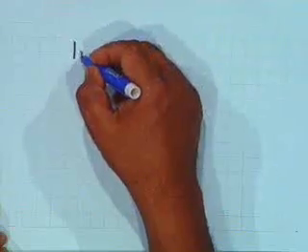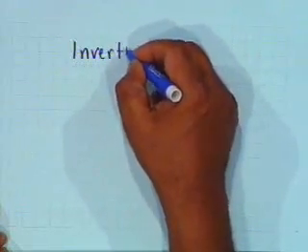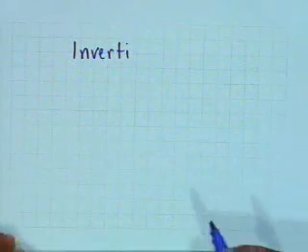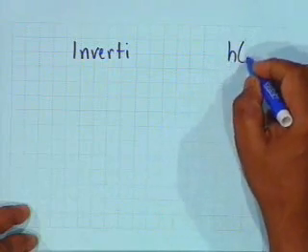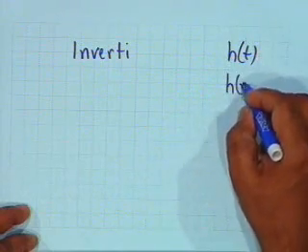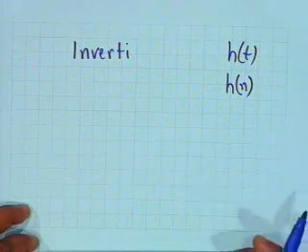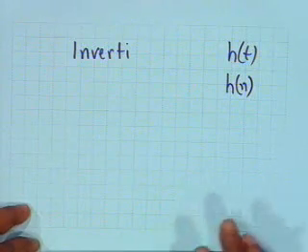Now, under what condition? The purpose of this discussion is to show to you that h of t or h of n, the unit impulse response in the continuous time case or the discrete time case, is adequate for describing the system completely. We have shown linearity, time invariance, we have shown memory or memory-less.